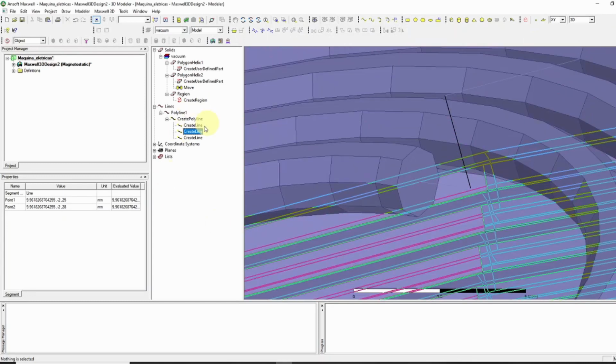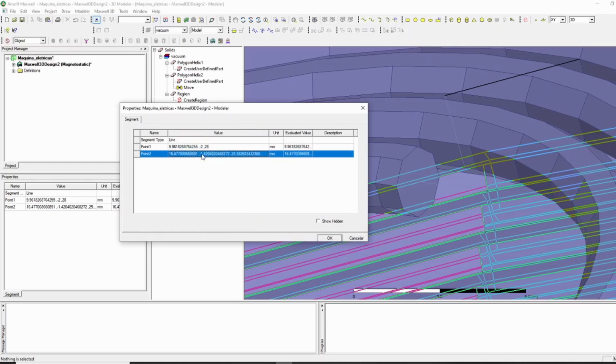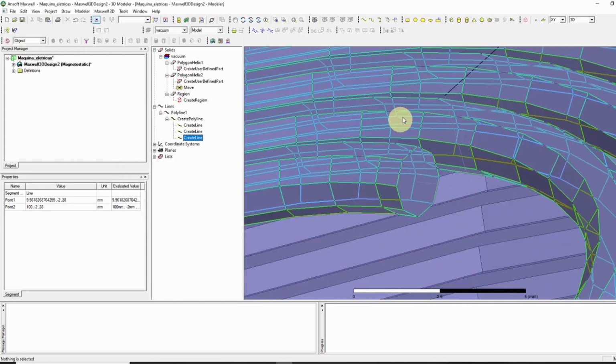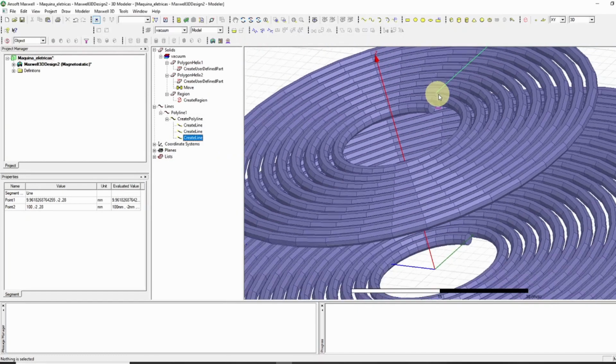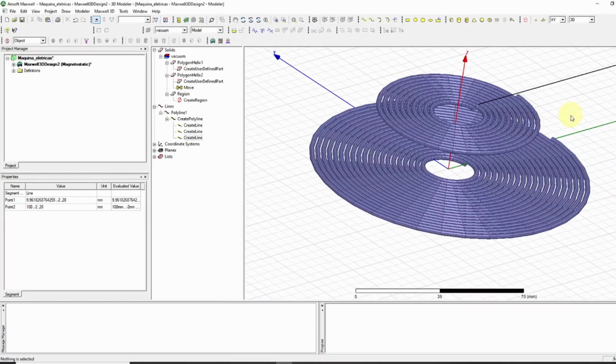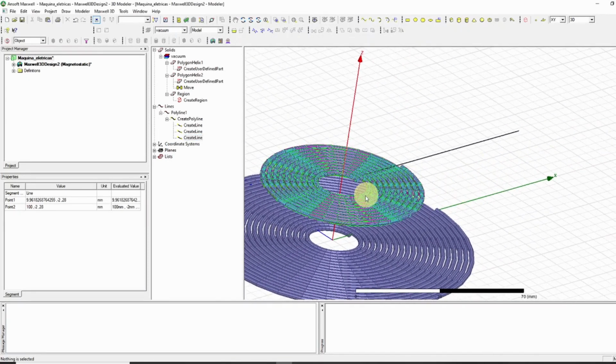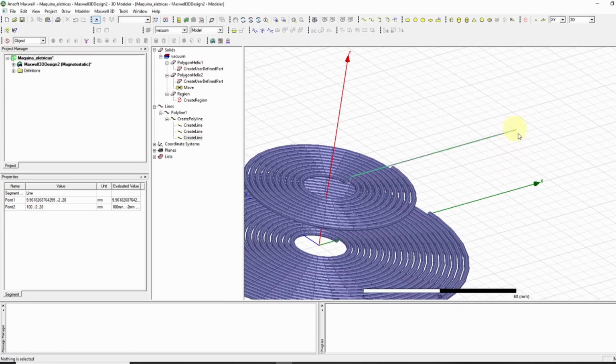And now I want only the line to go in the Z direction. So let's do the same thing here: copy and paste the initial part of the line and the end part of the line, and only change the x-axis. And I'm going to put it as 100. So now we have the line created. You can see it right here. So look, the line is going in that direction there. That's what we want. We're going to do the same thing with each one of the lines, and by doing that, we are going to have all of the lines touching the faces we want.